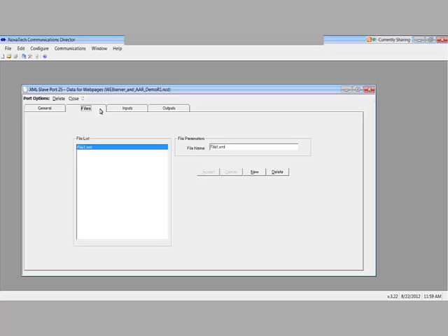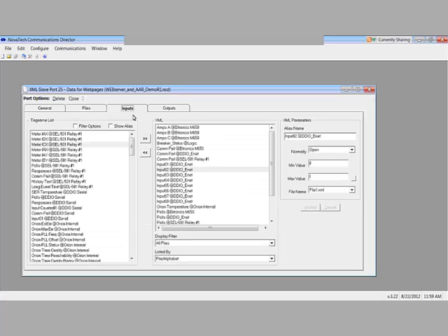If you had 25 web pages, and each web page may have 50 or 100 or 200 points in there, I'd suggest putting the points that are to be used to animate each of those web pages into their separate files. So this is where you could create a new file. You create a new file, file XML. And so you can create multiple XML files, and then when you select your points over here, you can designate which points go into which XML file.